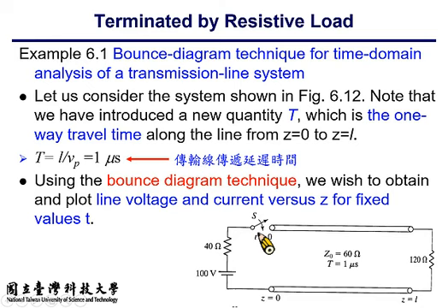In transmission lines such as coaxial cable or microstrip line, the velocity of propagation is about 2 times 10 to the 8th, about 66% of the velocity of light in free space. So the time delay of 1 microsecond is on the order of 200 to 300 meters.